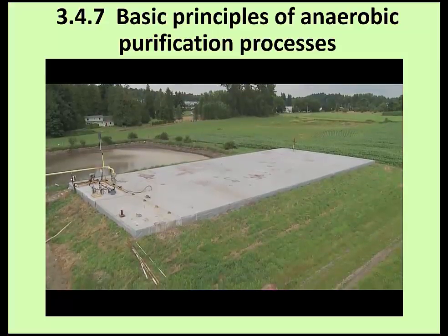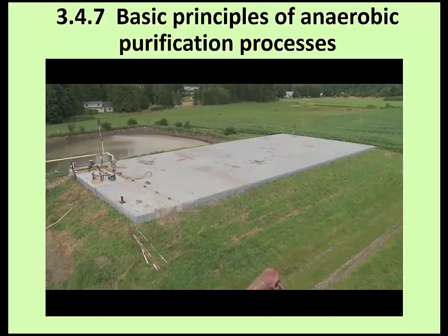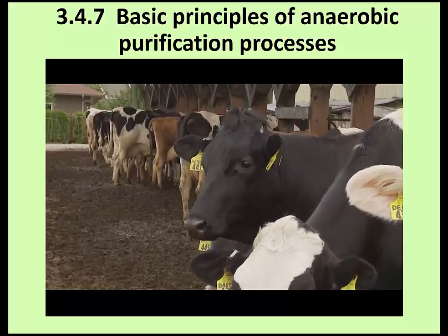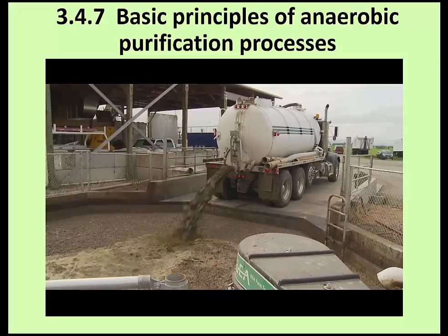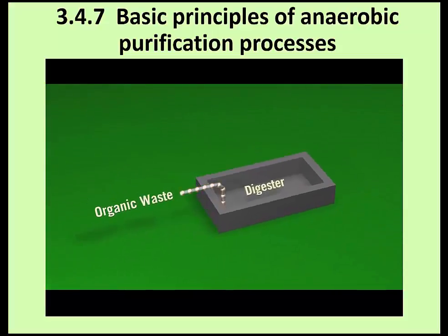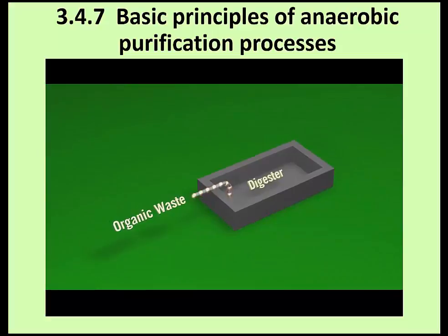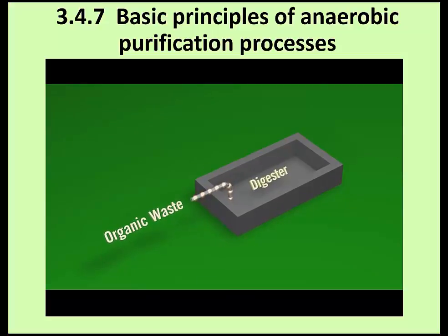At the center of the system is the digester itself, basically a sealed tank where the organic material is broken down. On this dairy farm, cow manure and potentially off-farm organics from the community are collected in a holding pit, then pumped into the digester. The tank mimics the digestion process of an animal's stomach. Inside, the liquid is heated, agitated, and mixed in an air-free environment.